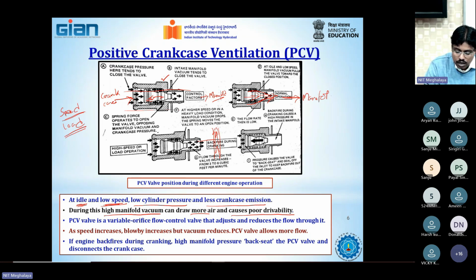When the amount of mass supplied through the main manifold is higher, the manifold pressure reduces. In the earlier case, at low load condition, it was much below atmospheric pressure. Now it is only slightly below atmospheric. That means the pressure drop is adjusted in such a way that the pressure inside the manifold is only slightly lower than atmospheric.